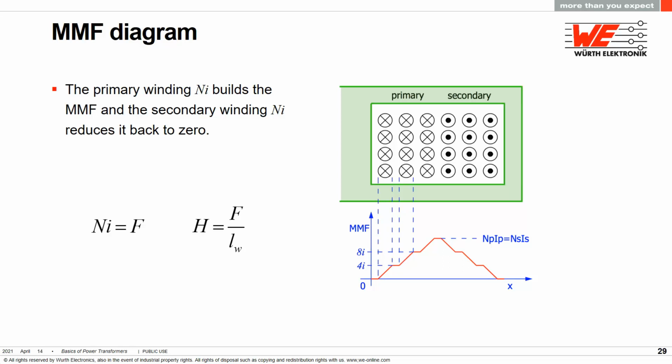out that the leakage inductance is stored energy, and the highest energy will be there where the greatest field intensity is, which is exactly between the primary and secondary winding. Sometimes shields are placed in this spot to either reduce the capacitance as a Faraday shield or for safety. Either way, this is the worst place because the strong magnetic field will induce eddy currents in the shield material, which is often copper foil, creating additional losses.